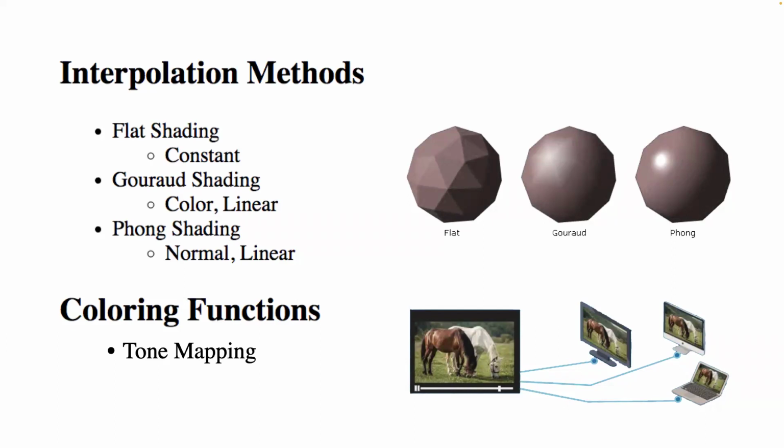The Phong shading method computes the normals for each vertex and interpolates the normal to pretend that the surface is not polygonal, but smooth. Then for each point, it uses that normal to compute the shading, and it is interpolated in that way.